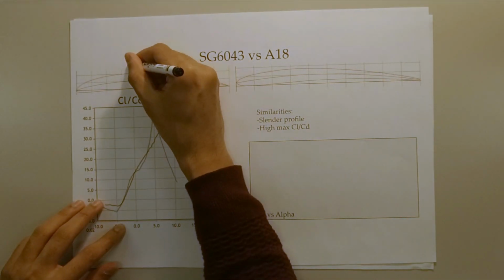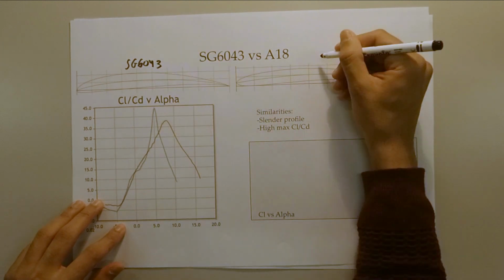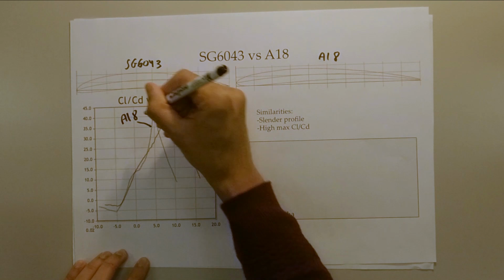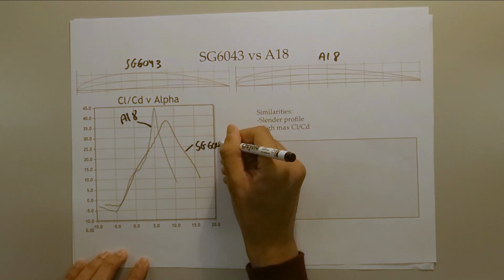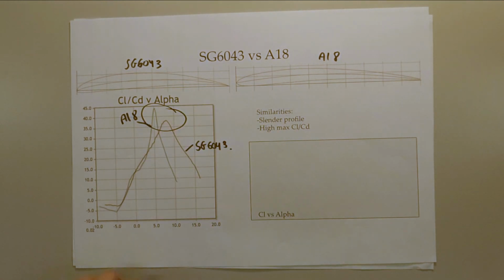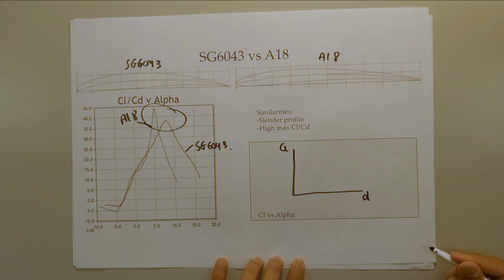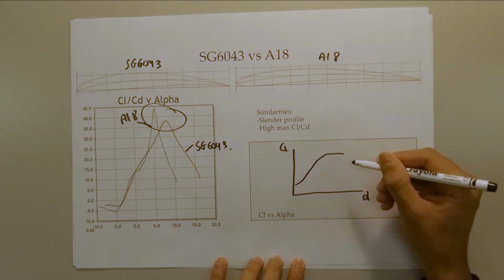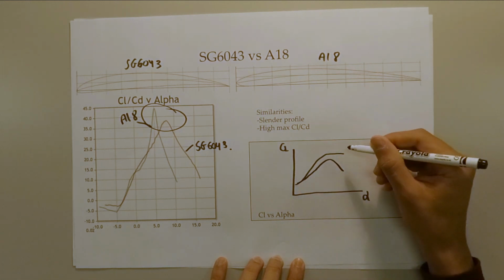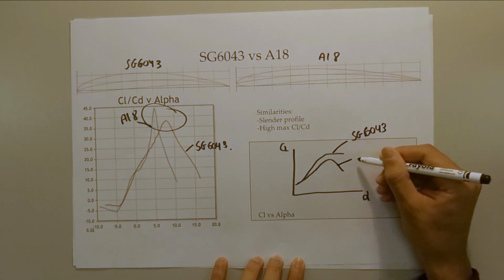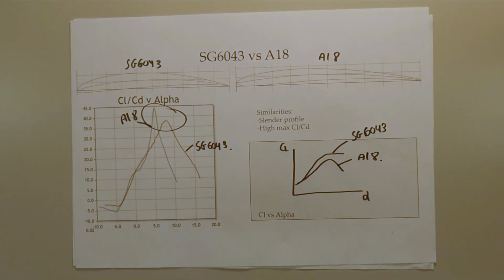The SG6043 and A18 airfoils were shortlisted due to the high lift-to-drag ratio. Although the A18 had a higher lift-to-drag ratio, its thin profile and sudden peak in stall would affect structural and off-design performance. The SG6043 airfoil was selected as this airfoil has been optimized for low Reynolds flows and experiences a plateau region around the stall, imposing a safety margin during testing.